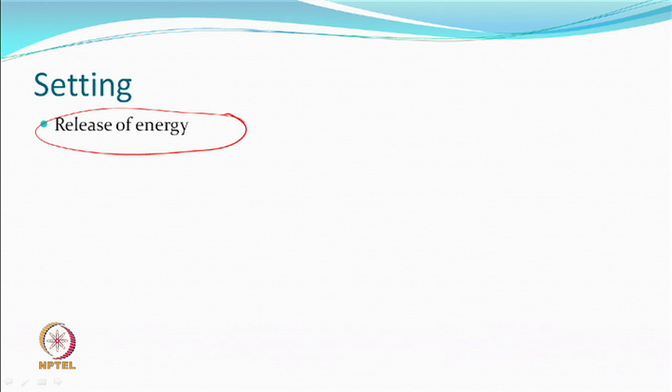So, all that is there. This is also in the same category of texturing processes. Setting, which is the key component, is by release of energy. That is why we can say that this is just like thermomechanical texturing, which relies on release of energy, as against what we discussed in the previous lecture, where we used a cross-linking agent, which is not setting by release of energy. So, this is going back to the same thing.